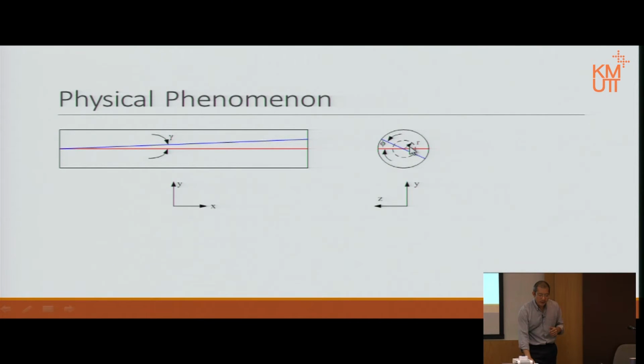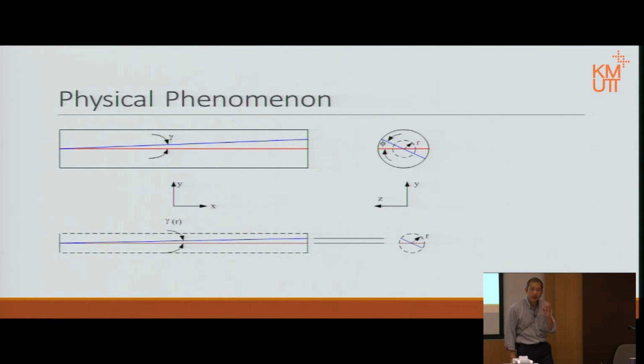Then if I draw just that, we will see that the angle here, because it is still from the end, is the same angle phi, the same angle of twist as that one there. However, when we relate back to the front view, we have this picture. Notice that gamma is smaller. Why? Because this gap here is smaller than that gap, but the length is still the total length.